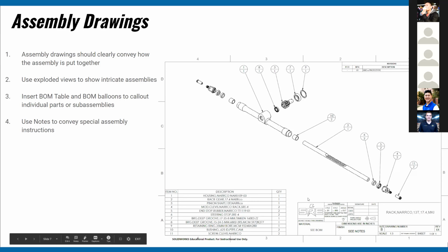What's also missing from this drawing is a next higher assembly callout. So usually you want to say what's the next highest assembly for this drawing. This would probably report up to steering, and then you would call out the entire steering assembly. That's really useful for when you just have a drawing and you need a reference back to it. Sometimes you can use the E-BOM or engineering BOM to look back at what assembly it reports to, but it's often convenient to have it in the title block. And then obviously it's missing the drawing number, and the update on the rev and whatnot.